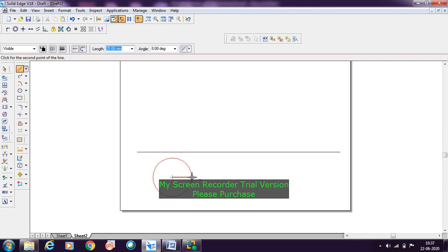In the system, how to do it? To start with, you need to draw one radius line. In order to divide the circle into 8 equal parts, you can also do it manually. Draw the vertical diameter and horizontal diameter, then draw the 45 degree line in this quadrant and project it backwards. Similarly, draw the 45 degree line in the other quadrant and project it backwards. But since I am giving the demo in the system, I will be using the radii options here.